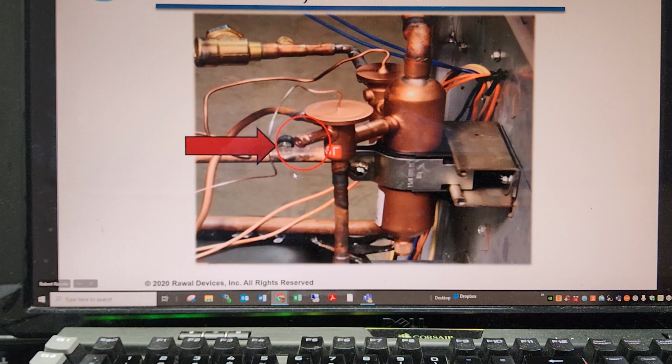Okay, this is very important. Never adjust the liquid injection valve. That liquid injection valve is preset from our factory. Adjusting that liquid injection valve will void the warranty of the valve. Where is it? The liquid injection valve is the other valve, not the one that has the adjustment screw on it. It's going to be the one that has the blue liquid line sticker on it. It's the one you're going to tee into your liquid line. Just don't adjust that one like we talked about before.